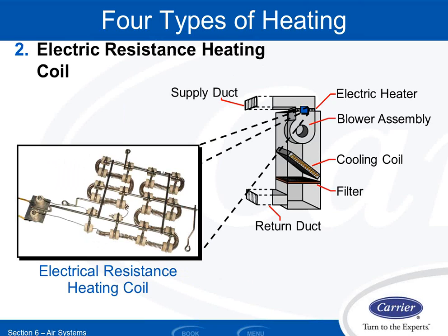It is probably the least costly from a first cost standpoint. The heaters are very light. They don't take up very much space. I don't have to run piping. I don't have to run gas lines. I just run electricity to it, which I was already running anyway for the fan, so I just run a little bit higher amperage, a little bit thicker gauge wire, etc. However, it's not typically the most energy efficient way to heat a space.